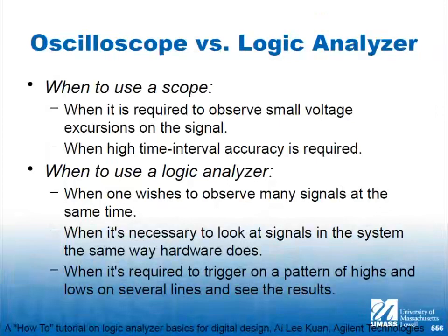Okay, but what we want is a very flexible triggering method. We don't want just a low to high on a single signal. We want to be able to set up complicated triggers. So let's picture going back into simulation. When you're in simulation, you put in a bunch of stimulus, and then you look at the response, and you have this large number of signals over a long time. And then you go looking for an event.